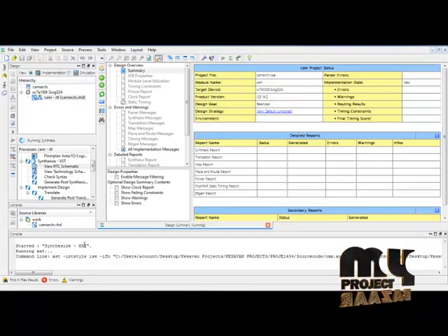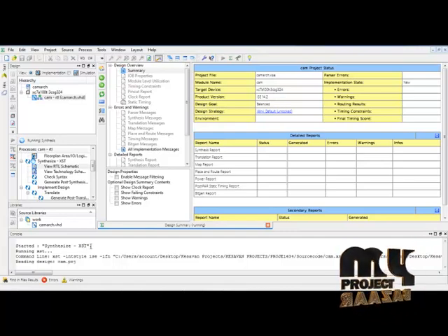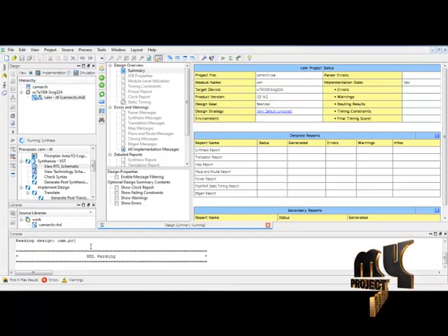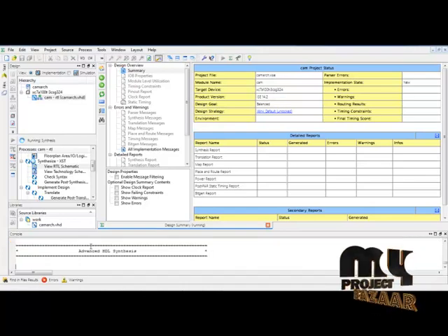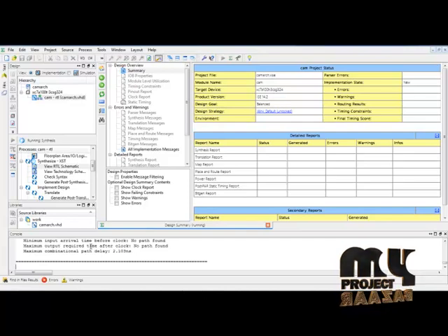If there are any errors or warnings, they will be displayed in the console window. This also checks the total number of LUTs and flip-flops present in the logical design. The RTL schematic displays only the schematic architecture of the logical operations provided in the code.